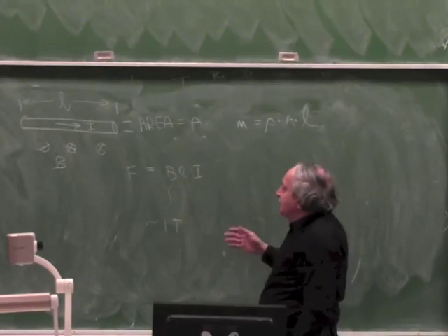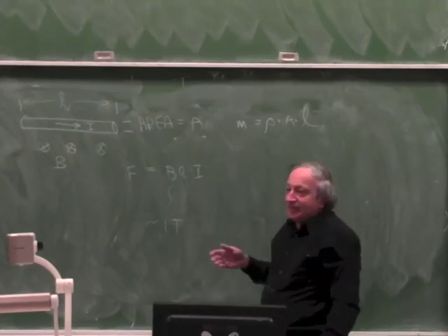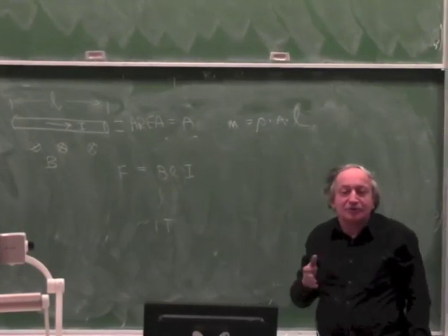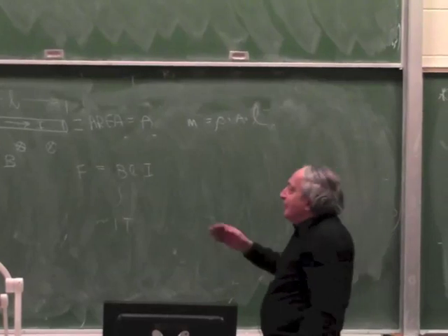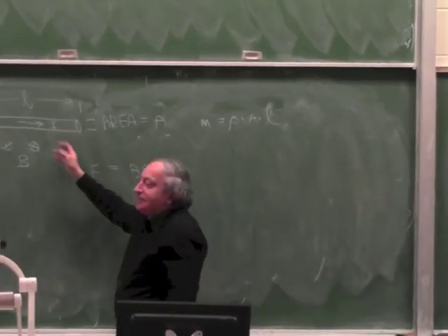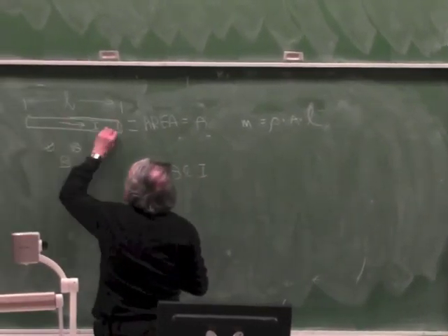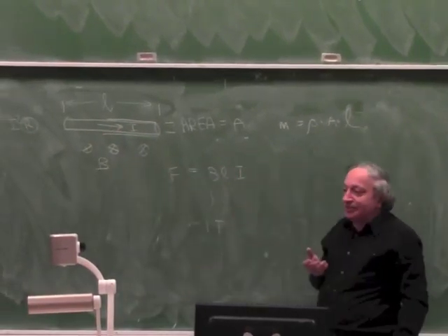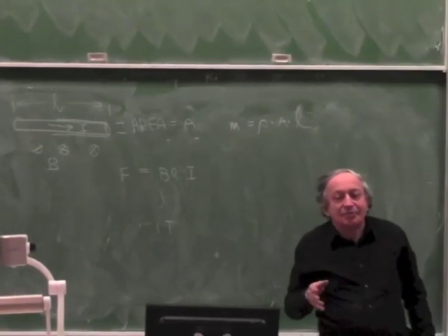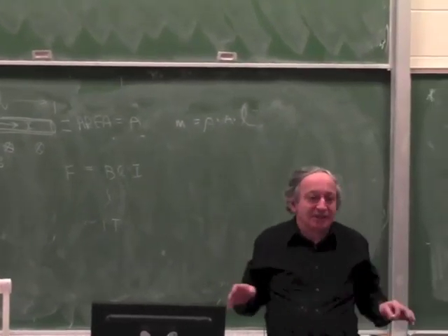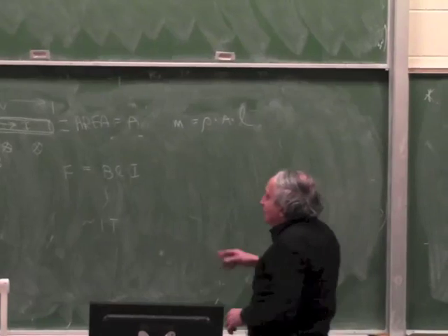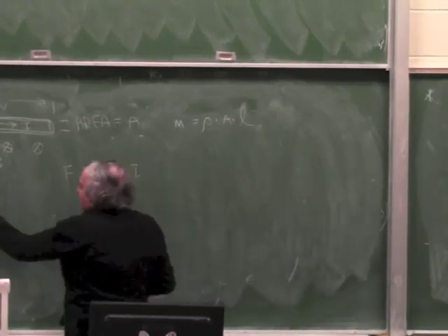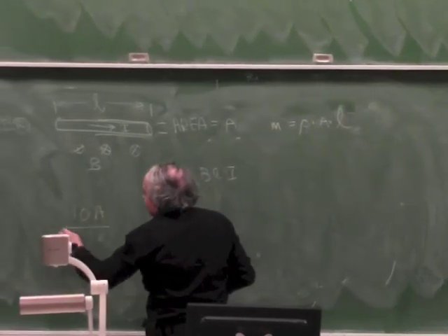So there must be a relationship between the maximum I and the area. And indeed, it's not a theoretical relationship, it's some rules of thumb. Because if the wire is heat resistant, let's say the wire has very good insulation, and I don't care if it heats up, of course I can run a bigger I through it. But a rule of thumb for all electromagnetic devices is that you don't want to run a current density of more than 10 amps per square millimeter.